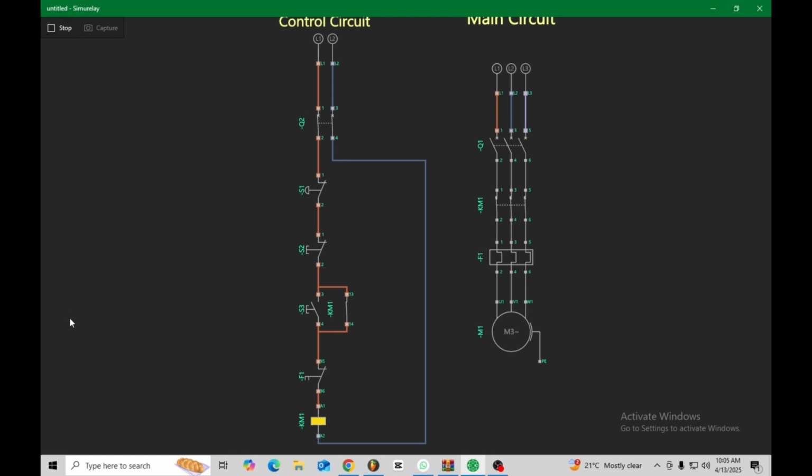I hit start. Notice the latching circuit energized as well and closed from normally open to closed, and my contactor closed. Now the motor should be spinning, but because I disconnected power from there just to make sure this is working first, to see if the wiring is correct. Okay, I'm going to hit my stop and let's see what happens now. So I hit stop and the contacts go open. Motor is not running, and cool.